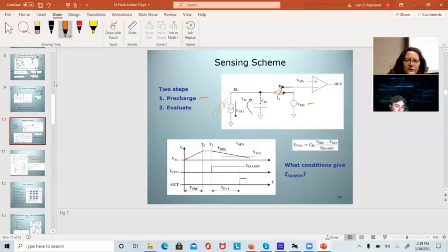So as this pre-charges, this voltage is going to go up linearly, and after we get to time t0, it's charged to our full level. We have to calculate the bit line capacitance to figure out how long we need to leave it charging to get to our desired voltage. And then we wait a little while, turn everything off and let it stabilize.